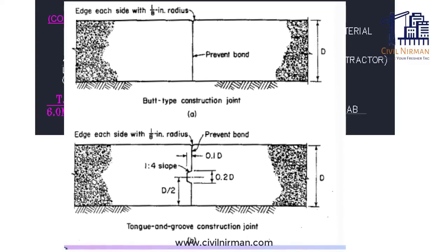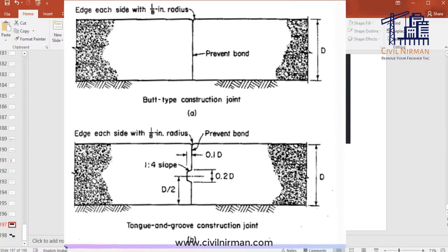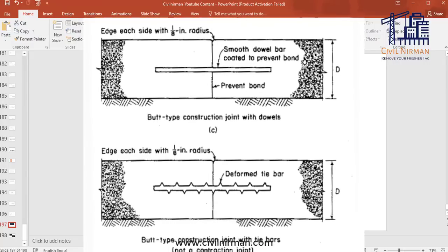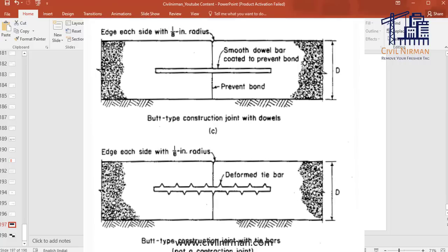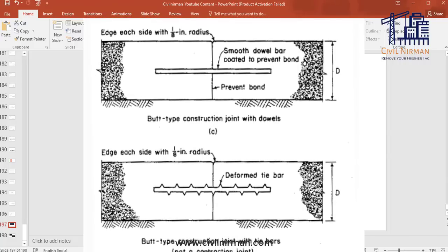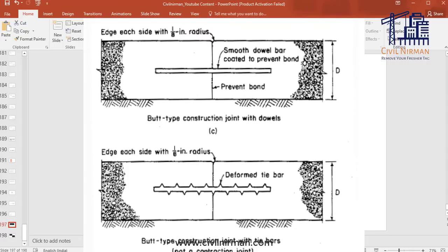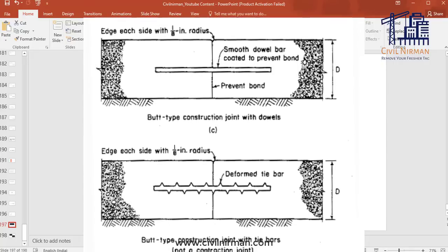Here I am representing a typical sketch just to give you a rough idea about the construction joint detail. See, a construction joint is essential if the size or the length of the concrete members exceeds some limit, right? Generally for short length concrete members, construction joints are not required, because for the expansion and contraction of concrete, the end of the concrete is too close. But when the length of the concrete members has exceeded a certain limit, there is no end point where this volume may change, and it may create a crack. Okay, so that's why it's important.